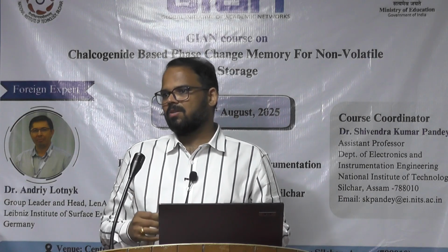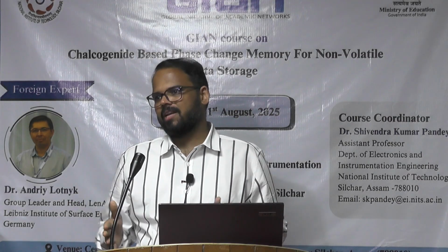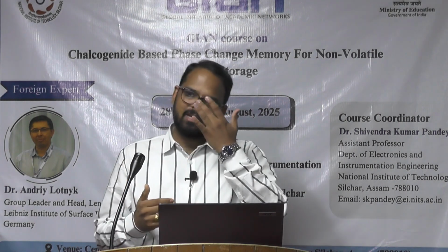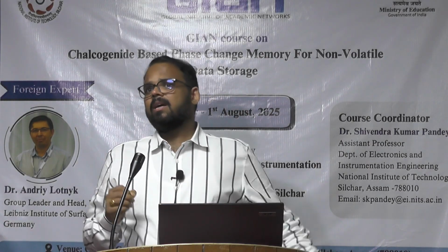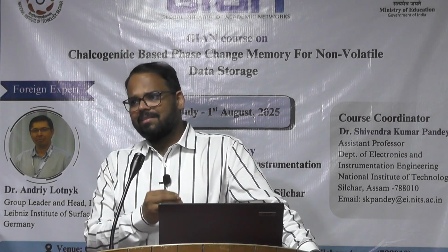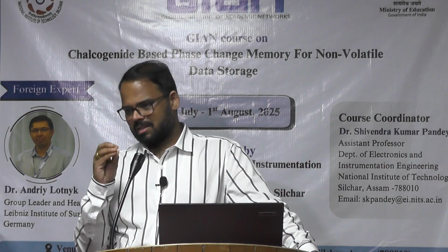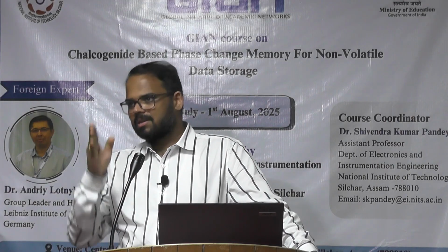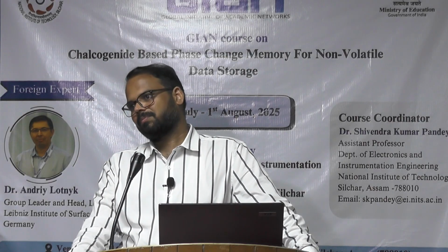But in the case of the highest rate, the crystallization temperature varies. So I tested this material at different heating rates. What I could see is that with a moderate heating rate, 5 degrees Celsius per minute, and with multiple tests at this particular rate, I got a stable transition from amorphous to crystalline. That's why I got this number.